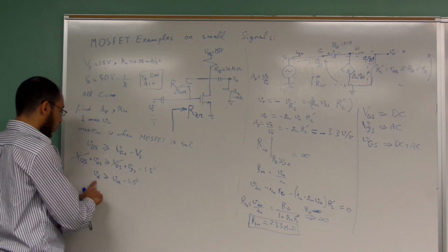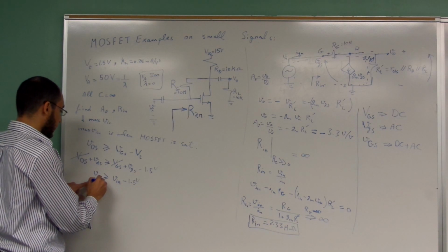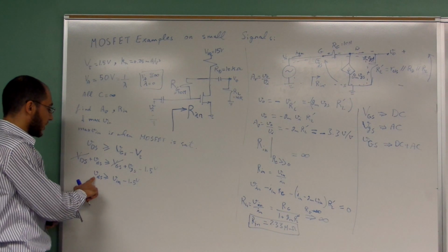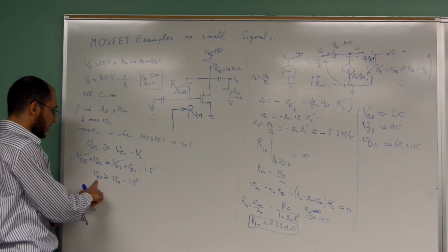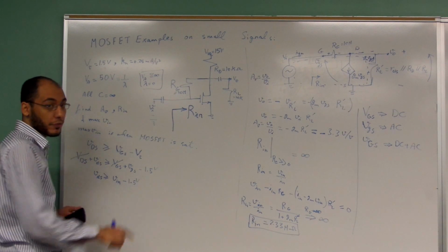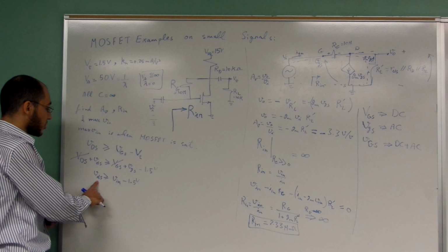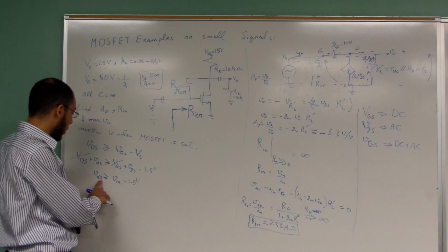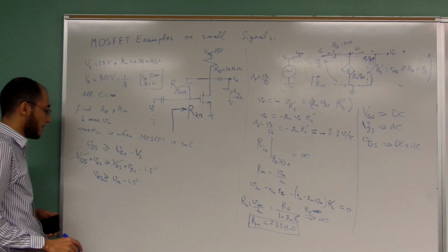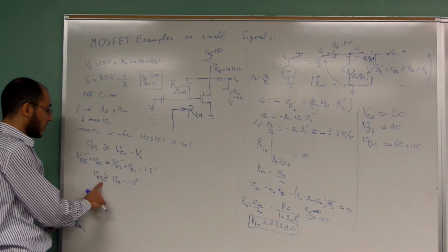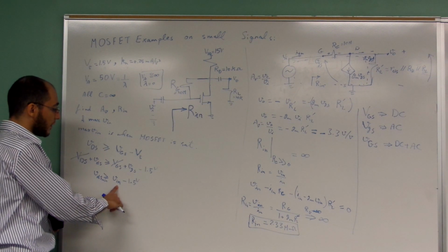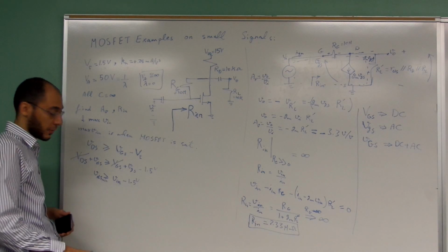Okay. What is the value of VD? It doesn't really matter whether you put it VDS or not. Okay, so what is this equation telling us? It's telling us that VDS has to be greater than the input voltage minus 1.5 volts. And this VDS is actually the minimum possible value of the drain to source. So it doesn't really matter if I write here minimum. Which means that the minimum value of the voltage of the drain to source has to be larger than V input minus 1.5.